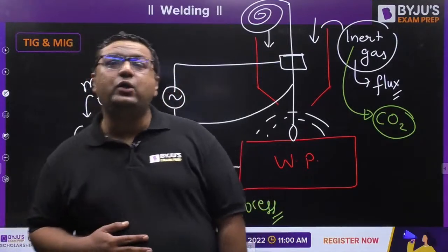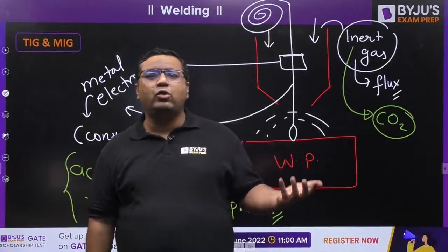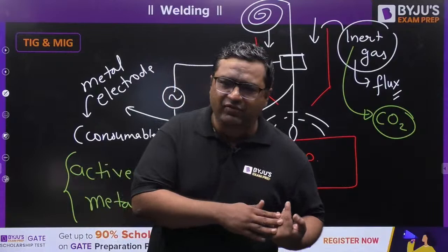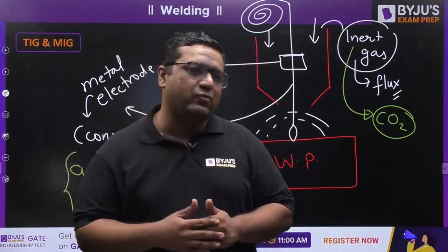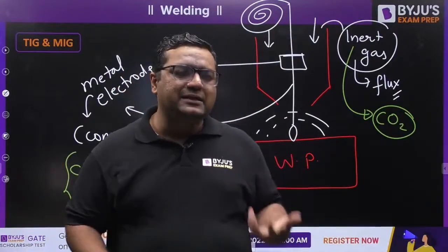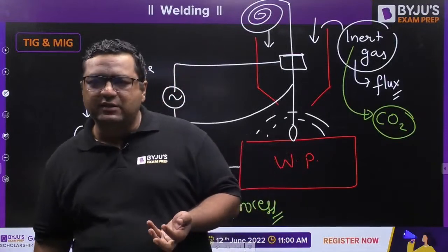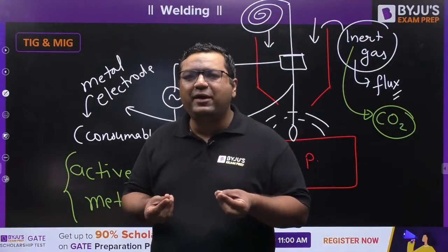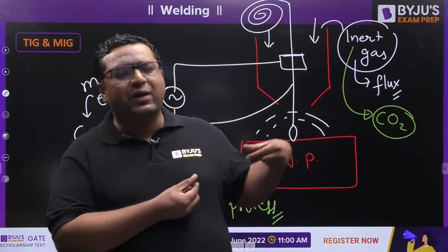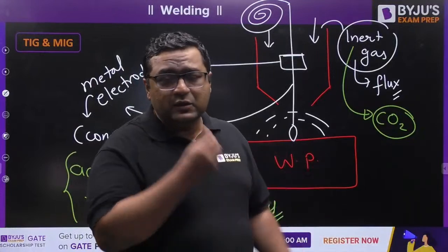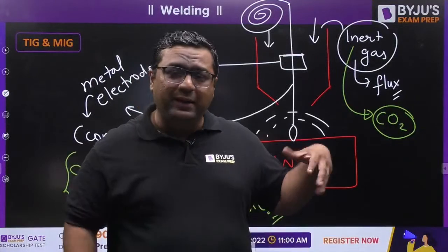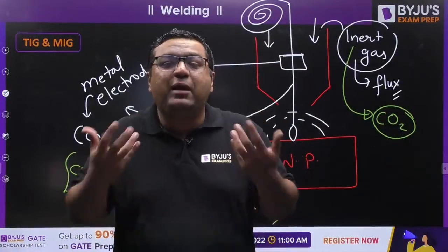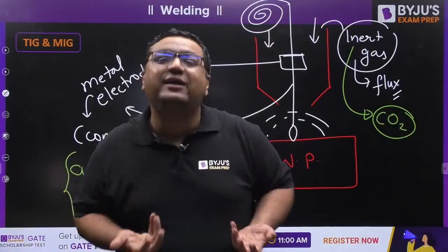Mondi Pawan, I already told you that when we were using molten flux, there were some issues: we had a limit over the flux, and the cost was more at that time also. When TIG was developed, it was majorly for aluminium and magnesium alloys, where we were joining very thin plates of aluminium and magnesium with the help of TIG. There were many other issues. We used inert gases to avoid the reaction, because aluminium and magnesium are very reactive metals.